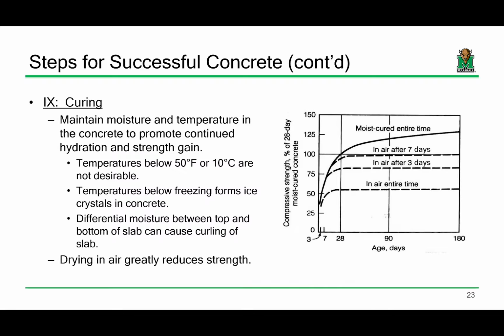We can get warping of the geometry of the slabs, called curling and whatnot, and we don't really like that. Drying, if you dry it in air, the strength goes down quite a bit. For example, if you look at compressive strength of concrete as a function of time, if you just dried it out in the air versus curing it in a moist environment, you get a lot better performance. So that's really what we're after.